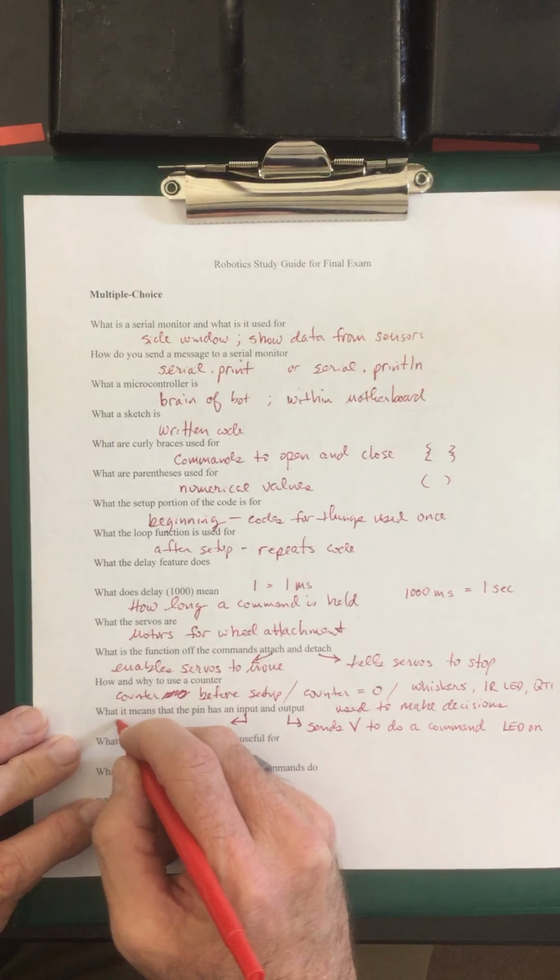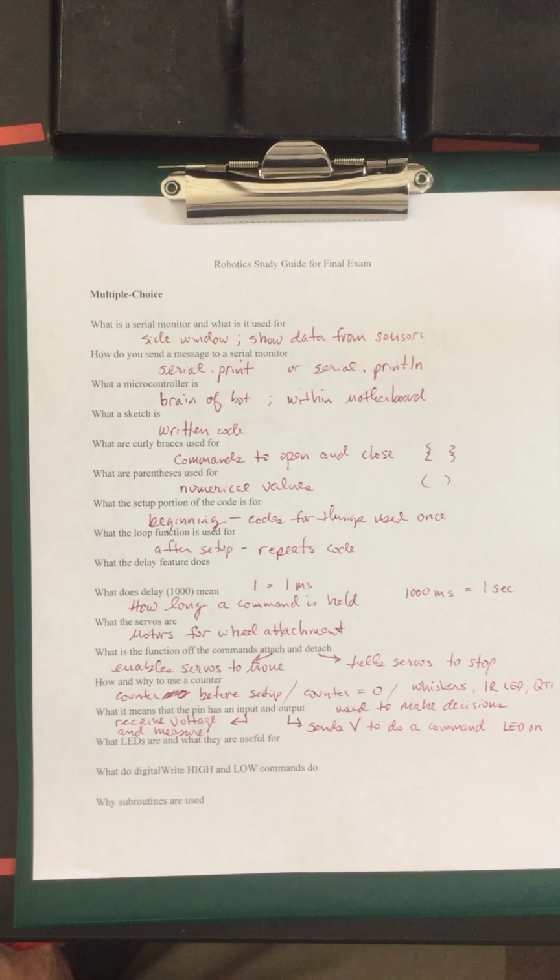If the whisker setup is on your robot, the voltage goes to the pin, and a 5 volt will register that whisker as 1. Now, if the whisker hits, it creates a different circuit, which transitions all of the voltage to go to the ground. In that case, none is going to the pin, so it would measure it as a 0. Those are the conditions for a whisker, for example.